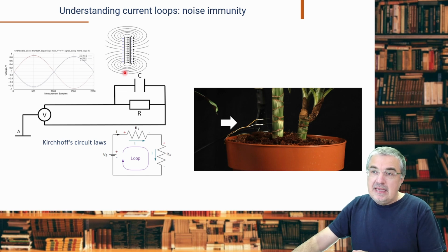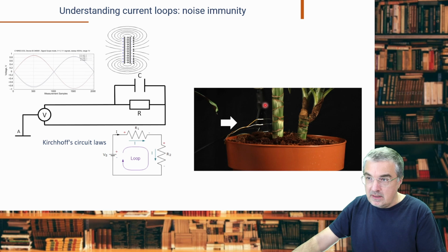The point is, again, that here we have a capacitive part that works with the electrical field. And whatever electrical field the system is surrounded by, for instance, here is a soil moisture stick, it also senses the electrical field; it produces an electrical field and senses it. And of course, if they are close enough to each other, this will influence the electrical field in the vicinity of these electrodes, and you will see interference between both sticks.